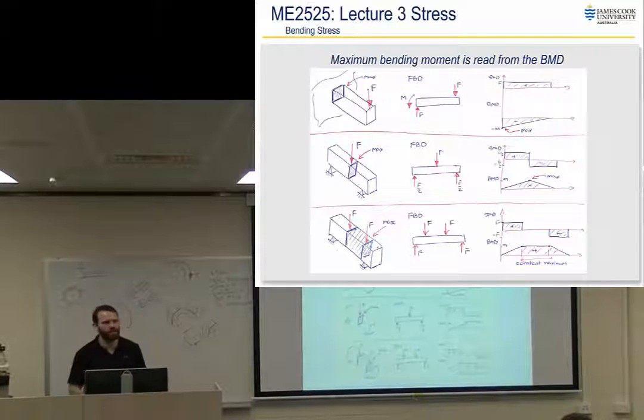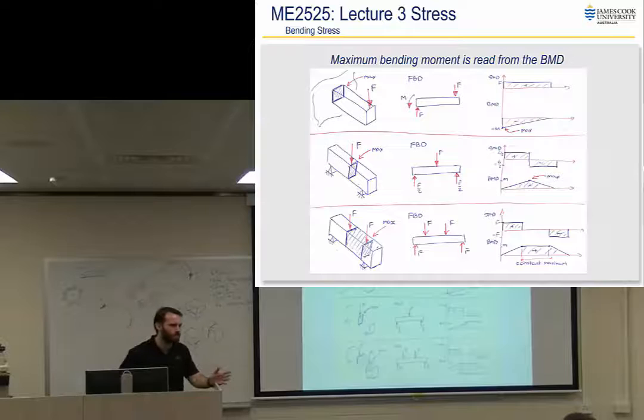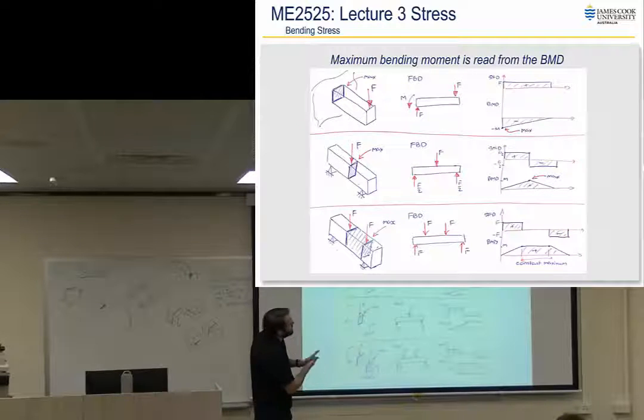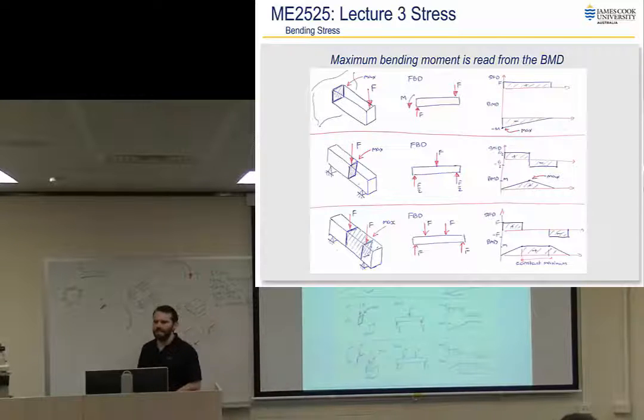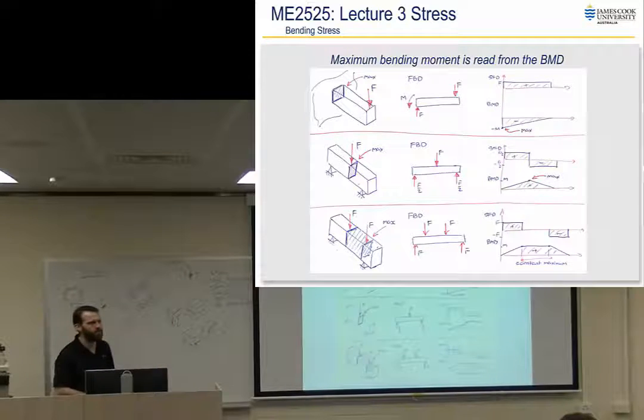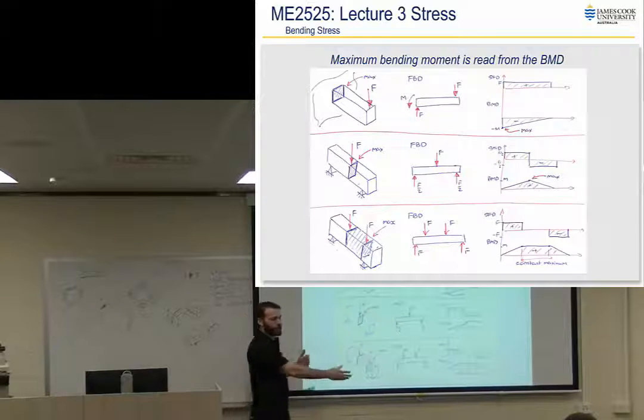All right, and that's useful in some circumstances if you want to do tests on bending stress and that kind of stuff. In this context, it just means that we have a funny looking bending moment diagram, but you calculate it the same way you calculate any bending moment diagram: calculate those sections, calculate some of the moments, and you're good. So, our bending moment diagram tells us what the value of M is, anywhere.